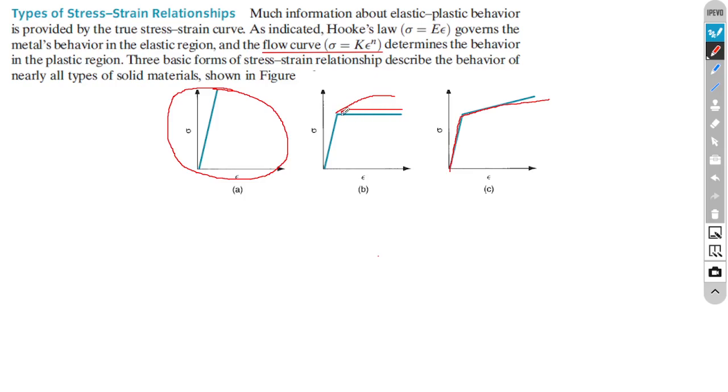But unfortunately for steel, the stress cannot remain the same during the deformation. It starts to increase. We say strain hardening. While we are straining, while we are deforming the body, it is going to be stronger.